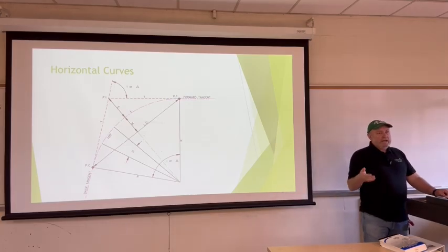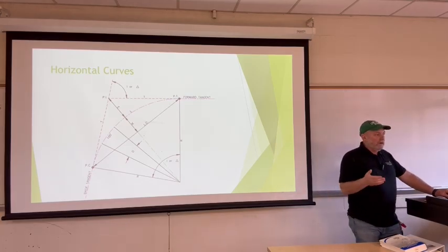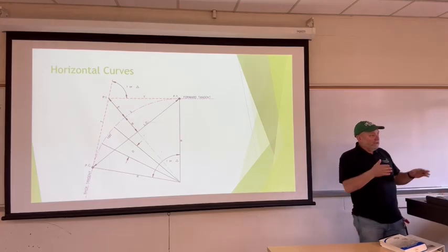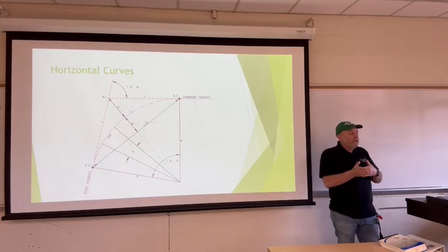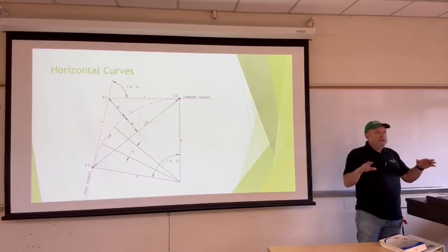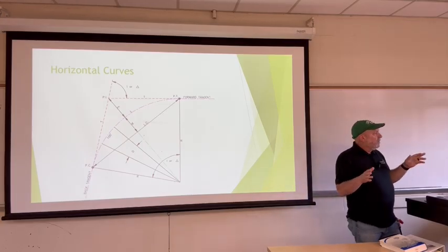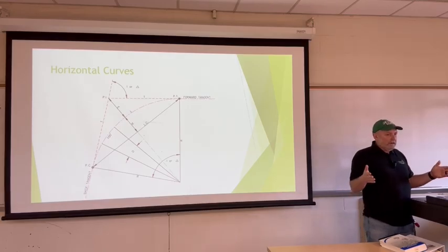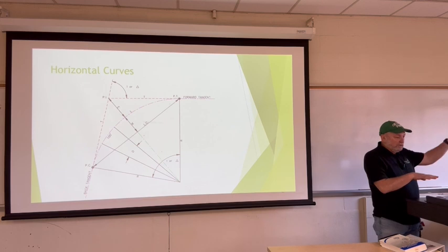There's also by easement. You can have a right of way by easement, which you might see a lot more out in more rural areas, where everybody's property lines go to the center line of the road, but there's still a right of way. That's an easement. Typically, in that case, if the road gets abandoned or vacated, that easement would expire, meaning the people still own that land.